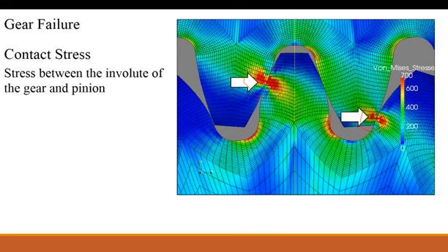The first point, right where the teeth meet, is called a contact stress. And this contact stress, again, it is a point where they can potentially fail. The failure will take place in the form of pitting and galling. Because there's a lot of stress here where they're put together, and at some point in time, that entire system is dependent on this one point of engagement. So it's important to understand what is going on there. This could help dictate the size of the gears that you use, the material you use, as well as the heat treat.